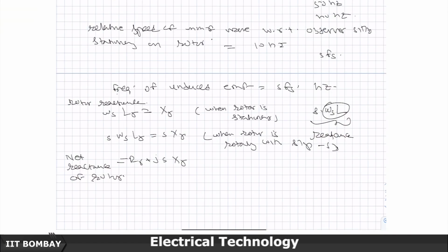Now the point is, in a rotating machine, see what you have seen in a transformer, there is a primary winding, there is a secondary winding, and there is a magnetic coupling between the two. In a sense, the induction machine is also called a generalized transformer. Now there is a primary side, it creates an MMF which is rotating in time.